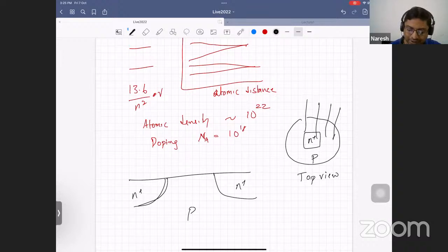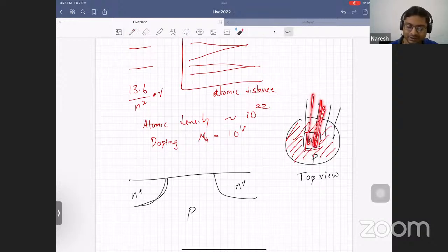To make sure that only in this area you have the implantation, you cover the rest of the area where you don't want the arsenic with a mask, and open the window only where you want the arsenic atoms. Through that, arsenic atoms will hit the substrate and dope that particular region.